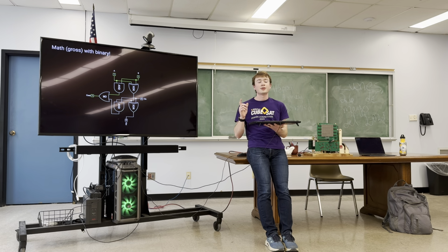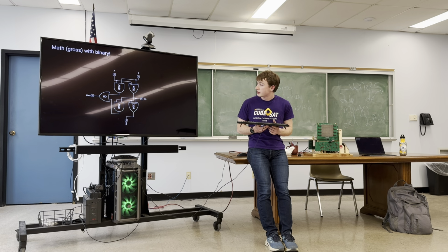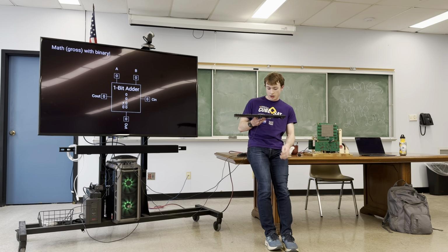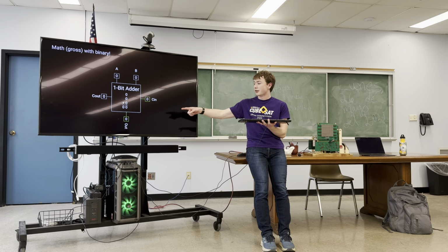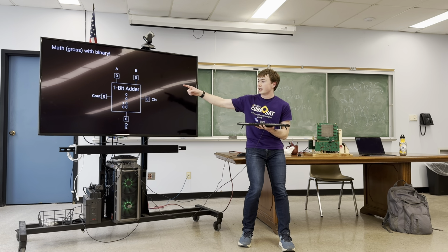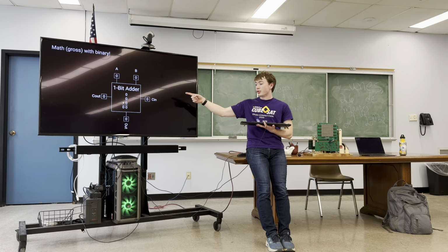All right, because binary numbers can be built out of bits, and logic gates do operations on bits, you can use logic gates to do math with binary numbers. So this is an adder. There are 3 inputs: the 2 inputs from the numbers, and then the carry input and carry output. Those will become important. Notice how the output is 1 because it's just adding 1 to a bunch of zeros for each of the inputs they're on.